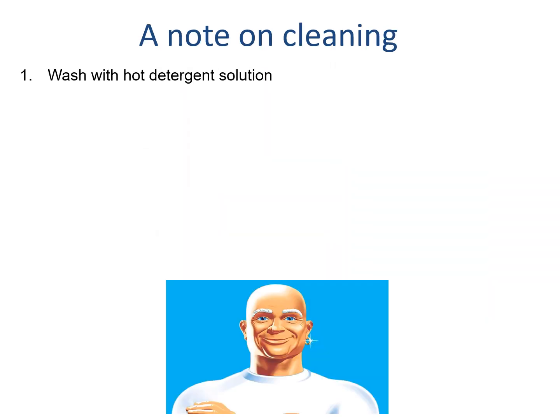And finally, a note on cleaning. When we clean, we need to remove both organic and inorganic contaminants. Organic contaminants require detergent to actually dissolve them, because like dissolves like, and the detergent has a long nonpolar chain. Inorganic contaminants require DI water. On some occasions, salts with limited solubility are removed by nitric acid.